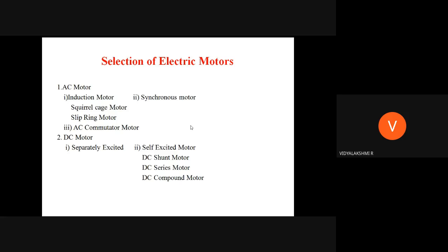Compared to AC motor, DC motor is expensive and periodic maintenance is needed, because it requires commutator and brushes. And if my supply is AC, we need a converter to convert my AC into DC. Again, the total cost of the system will be increasing more. And DC motor is only used when AC is not suitable to fulfill the special requirements. There I can use the DC drives.